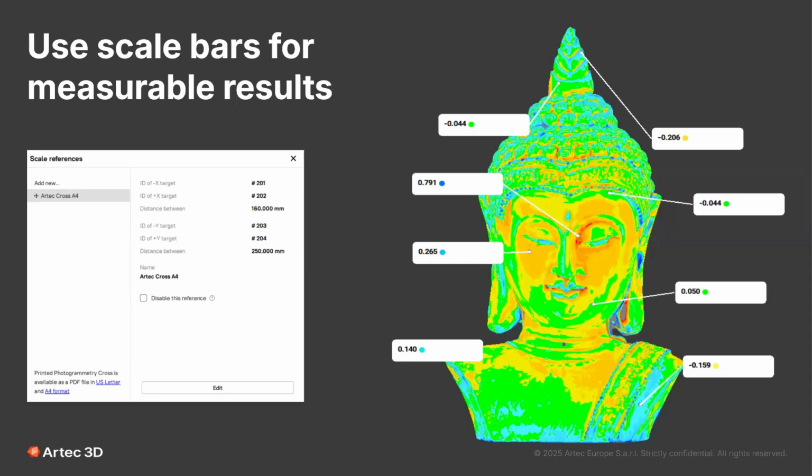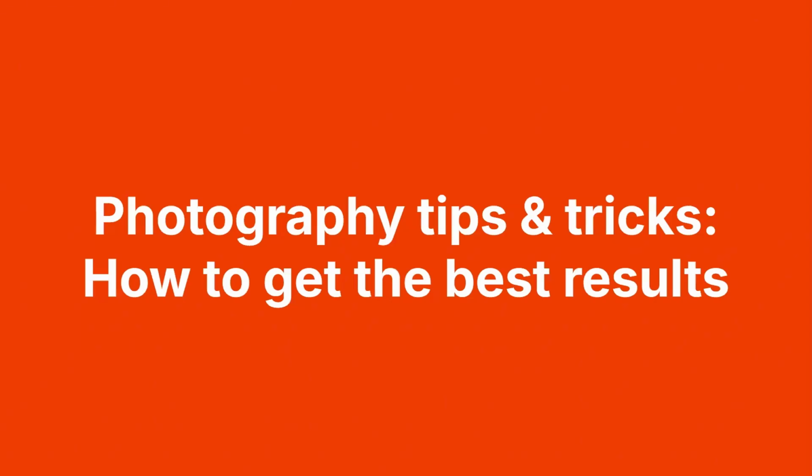Yeah, and in areas which have a lot of features, we actually have quite good and quite accurate reconstruction. So this is one more important part about photogrammetry, that it requires features. So the more features that you have in some particular area, generally the better accuracy you will be able to achieve there. So now let's move on to the next part.